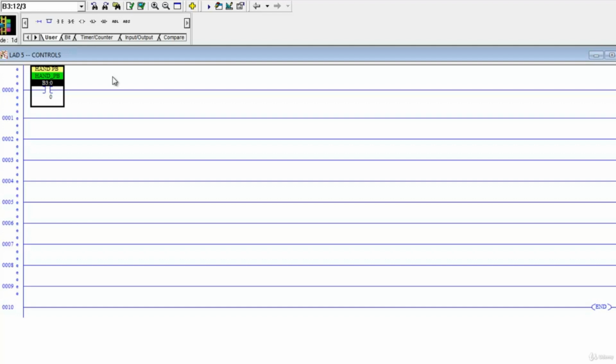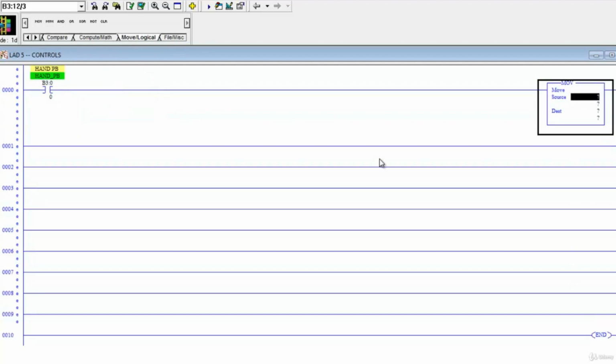So we're going to use an integer value to store the state. We can't obviously use a bit because a bit only has 2 possibilities, 0 and 1. The next alternative for us is an integer, and that can store 3 or plenty more values. So let's go ahead and use a move command. And we're going to call hand state 1,